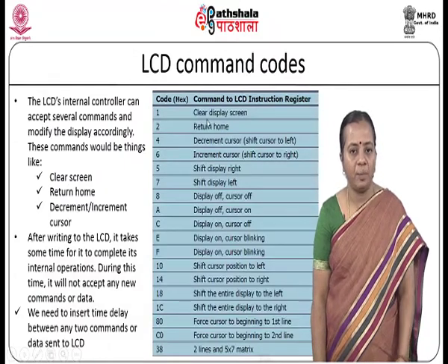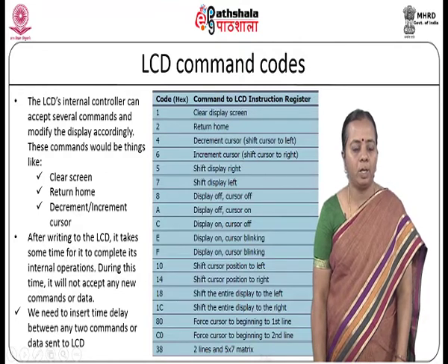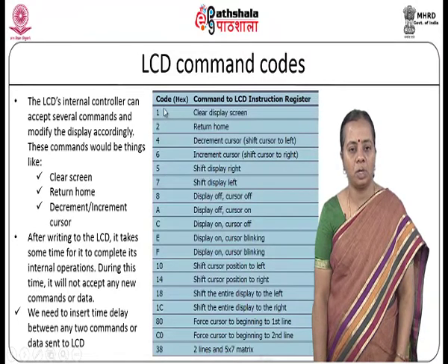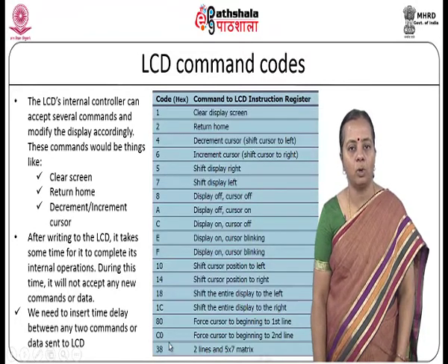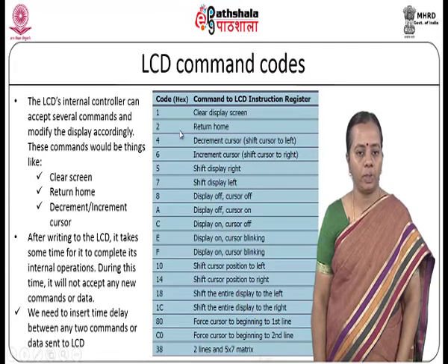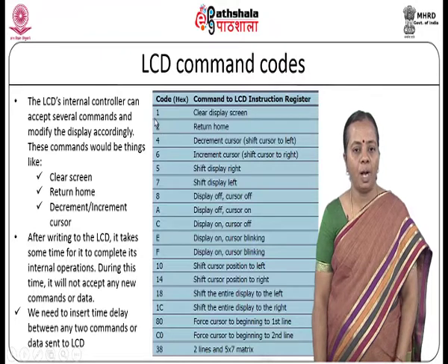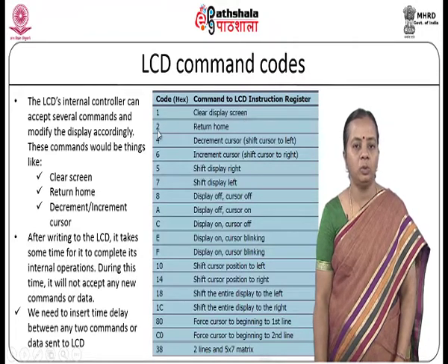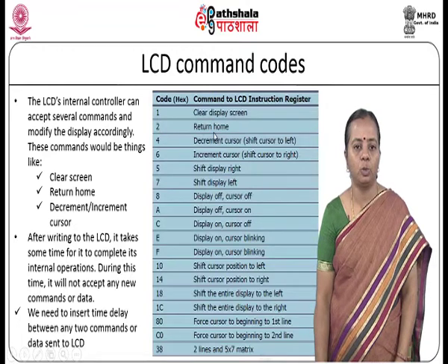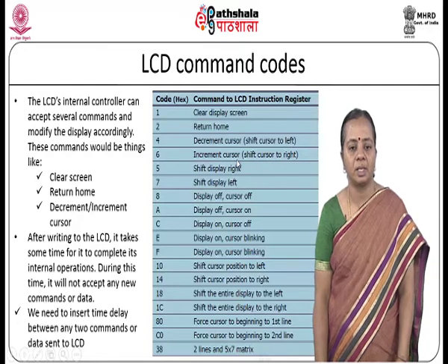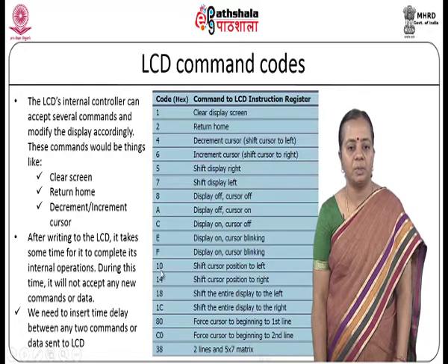These are the commands we should know when we want to operate the LCD. These are all hex codes, and we have to send the code as a hex code so that the LCD understands what we are trying to do. If I send 1, it means clear display screen. If I send 2, it means return to home. If I send 6, it means increment cursor.